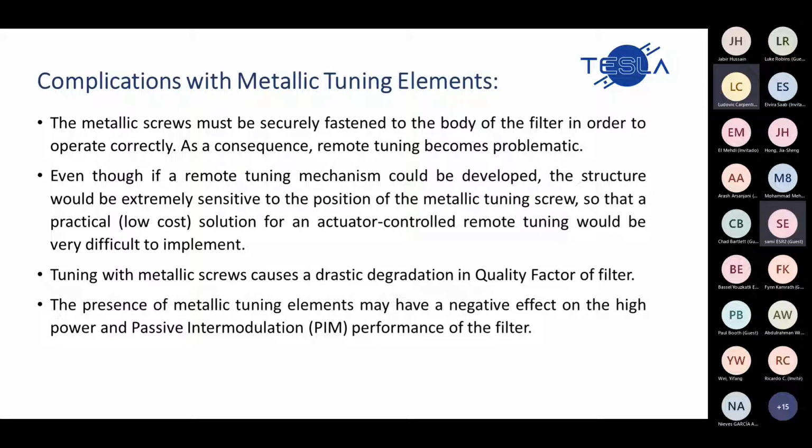One more thing associated with the metallic tuning is that it is very sensitive to the position of the height of the tuning screw. As we are using some low cost stepper motor or actuator motor, it's very hard to control those types of motors with metallic screws. Use of a metallic screw also degrades the quality factor of the filter very drastically.